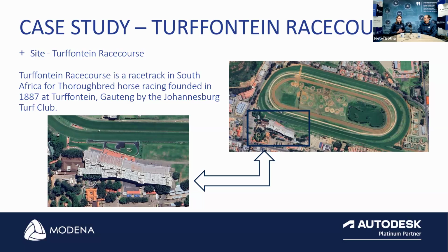So it's really understanding your client's needs. Are we doing this just for a spatial layout? Are we just going to do a basic LOD1 building just to show geometric positions and do a space plan, which we can do quick and easy? Or are we doing a basic architectural model where we want certain building elements like the windows, the doors, the floors, everything indicated? Or are we stepping it even more up from there? Are we adding structural components? Are we adding mechanical, electrical, and piping components? Is that some of the information that we would need?